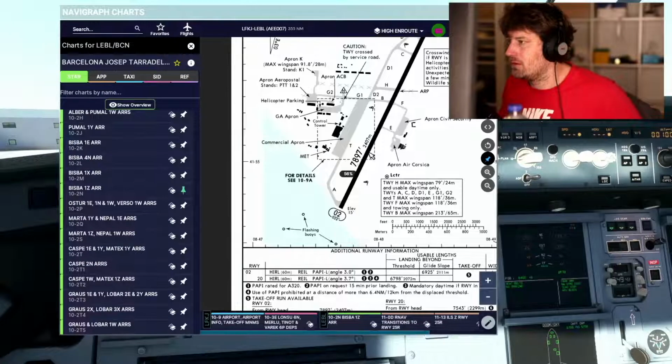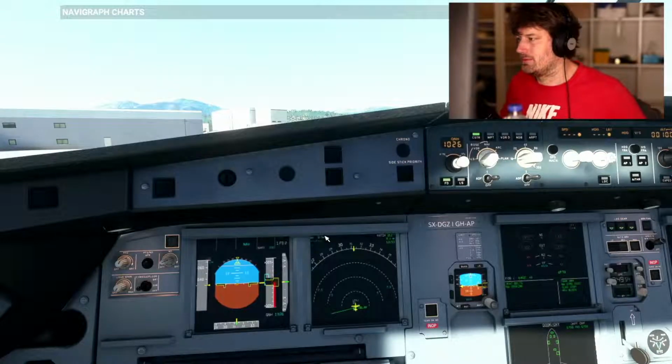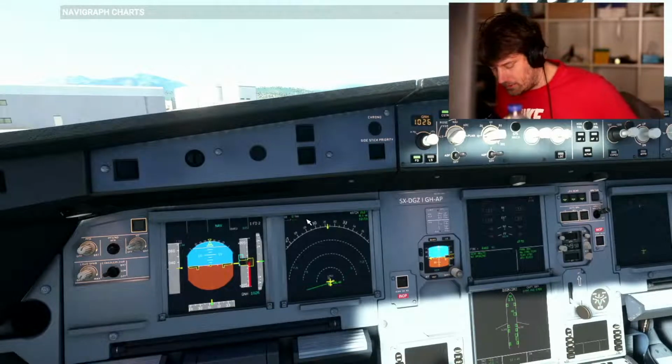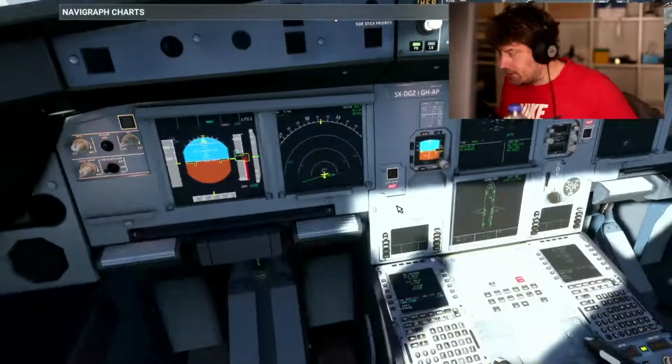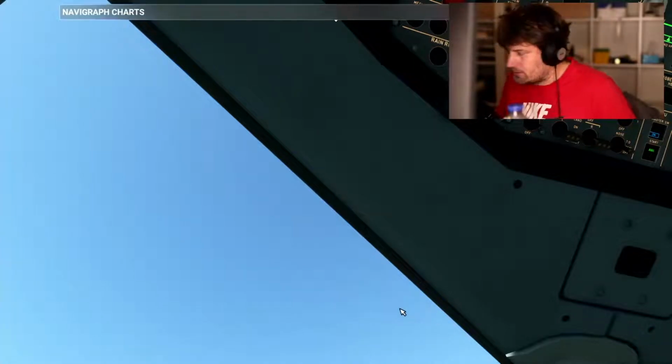We're parked here, and we have to taxi up north, so pushback facing north to go to runway 20. Windows and doors are closed, cockpit door is also closed, fuel pumps are on, beacon is not on yet. Let's turn on the beacon here. Steering pin in, transponder to auto. Let's put the transponder to auto.